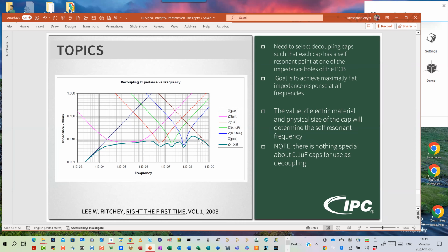Then yes, if you have designed this plane pair correctly with the power distribution network, your plane will be able to instantaneously respond to that switching demand, and the caps are just refilling the plane. Even if you put them close, all they're doing is refilling the plane from a closer distance, but a plane is a plane. It doesn't matter where the charge comes from. It's just charge.